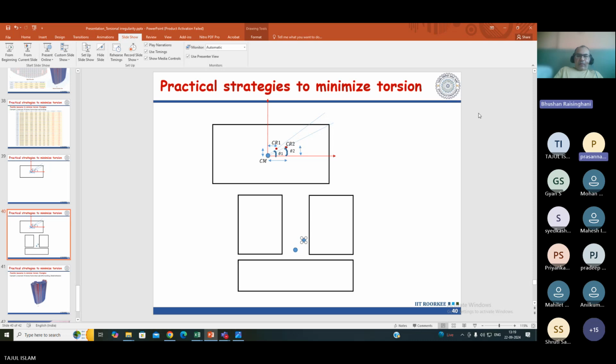So if you want to have a corridor in between the two buildings, you can have an expansion gap, or some bearings are also there. You can keep it on that if required. Not on all floors; if it is on all floors, then it is quite difficult. If it is on a specific floor, then you can put it on a bearing. If it is on all floors, then the only way is an expansion joint, or you do dynamic time history analysis.